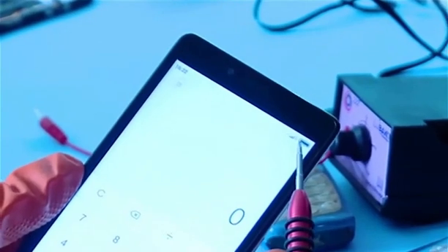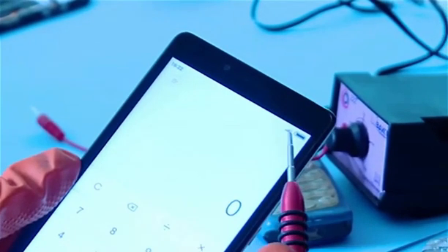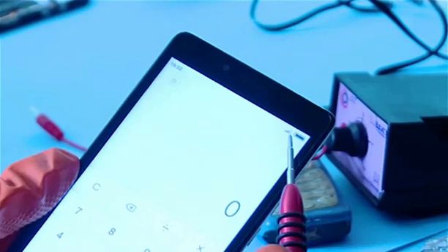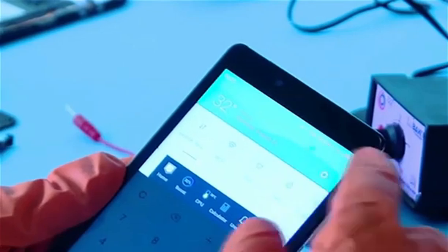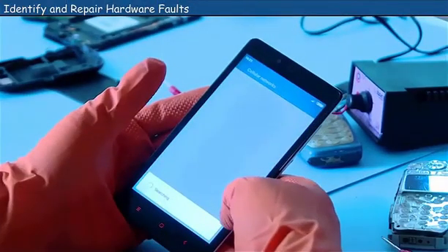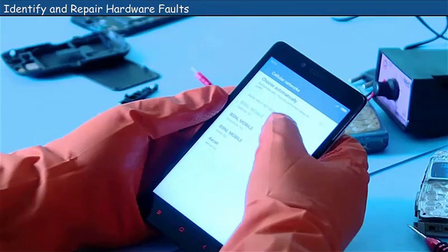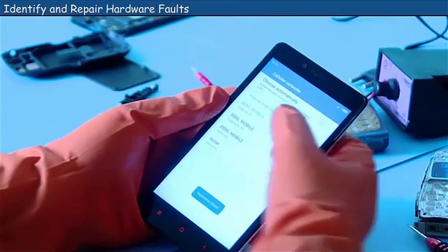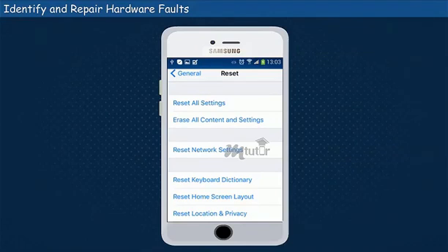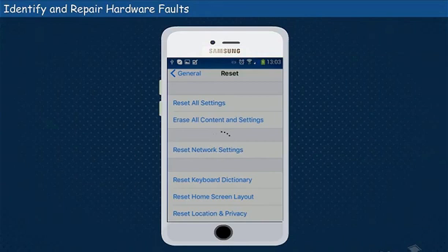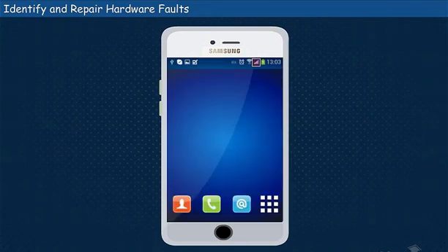If the network signal is weak, then the fault might be in the tower signal or in the network antenna. To check the tower signal, go to Network Settings and click Manual Mode. Now, it displays the list of networks in the range. Click on the registered network and check for the signal strength. If the problem persists, reset the network settings and check again. Most of the time, the problem resolves, else the problem is considered to be in the hardware component.